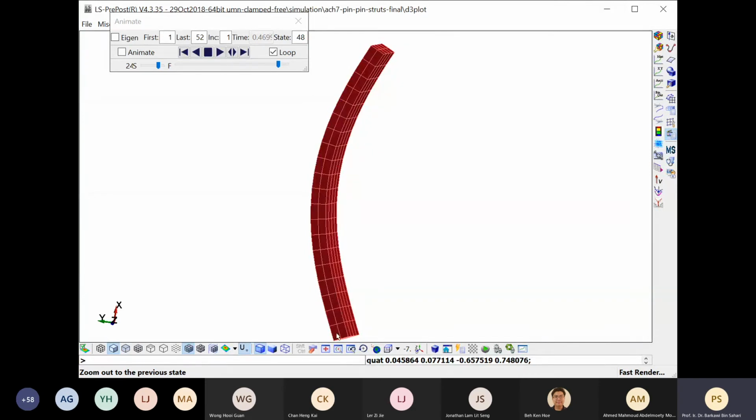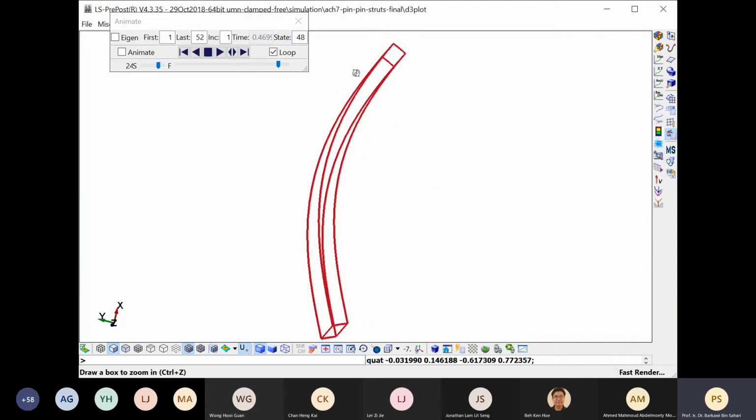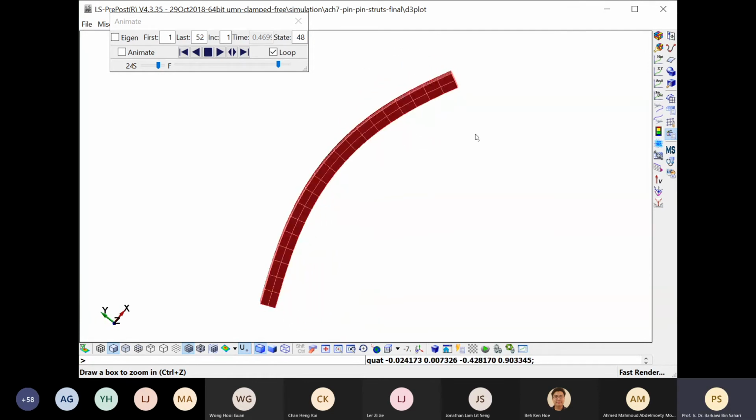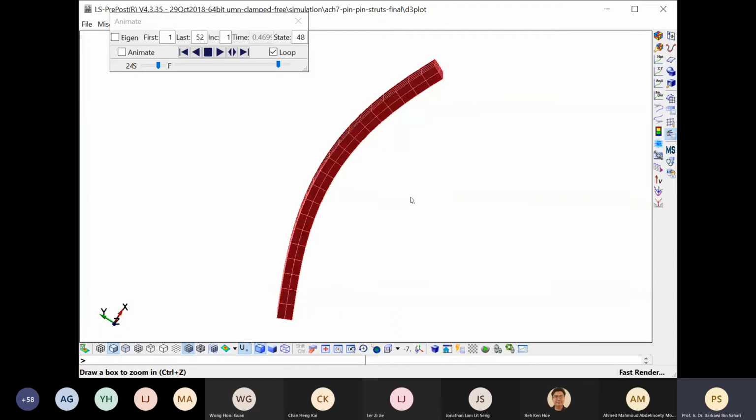Now, I don't have the result for bending moment on this particular simulation, but at 0 bending moment, we expect 0 bending stress. And bending stress is sigma x on this simulation software that I'm using.